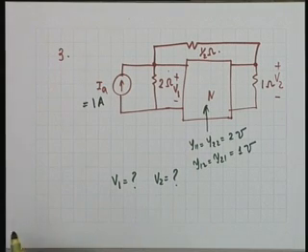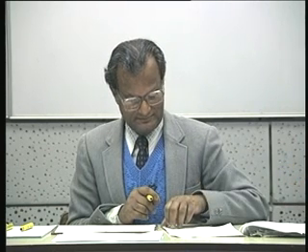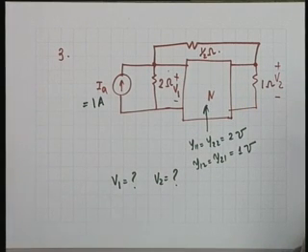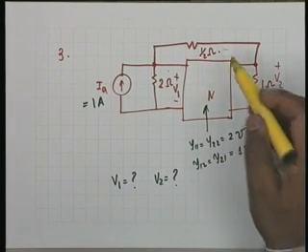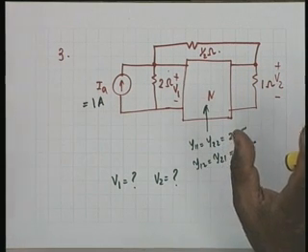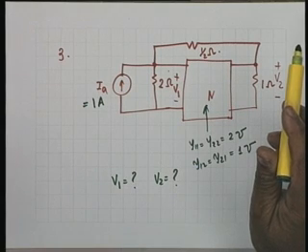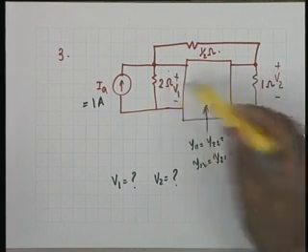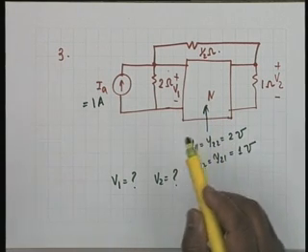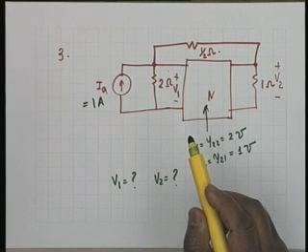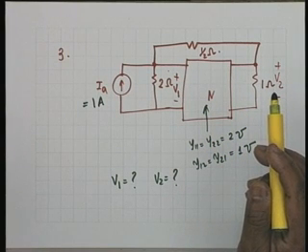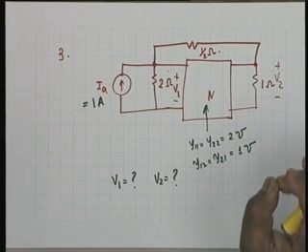Let's have suggestions. Replace this by a pi network. Can we replace this by a pi network? No. We cannot, because what you are trying to do is to view this as a parallel connection of two networks, right? Parallel connection, half mhos, 2 ohms, 1 ohm. But it is not given that these two are connected together. So you cannot make a parallel connection, because this could be truly a 4-terminal network. Agreed? This is the temptation, this is the pothole.